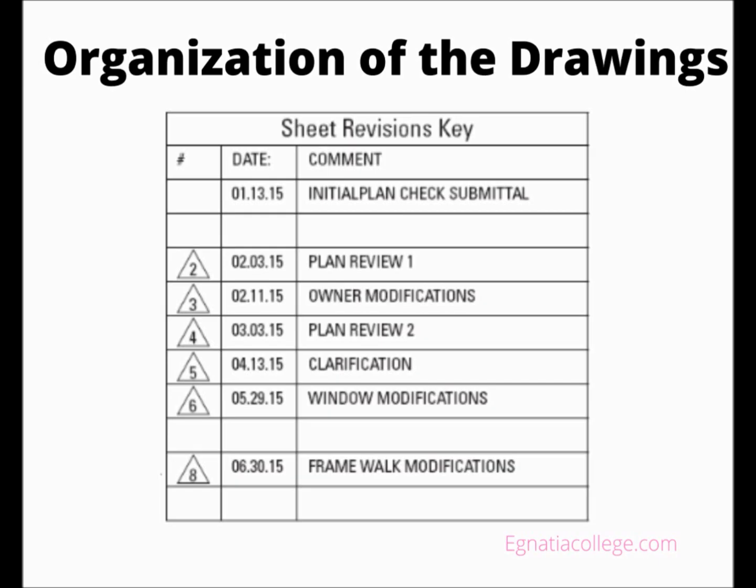Graphic legend. Explains the symbols used in this drawing set. Some may be conventional symbols used throughout the industry and some may be peculiar to this drawing set. Abbreviations. Some of these abbreviations are customary throughout the industry. Some customary in the region in which this work is done. And some may be peculiar to this drawing set. Without this index of abbreviations, some, such as the difference between P/L and PL, might be confusing.